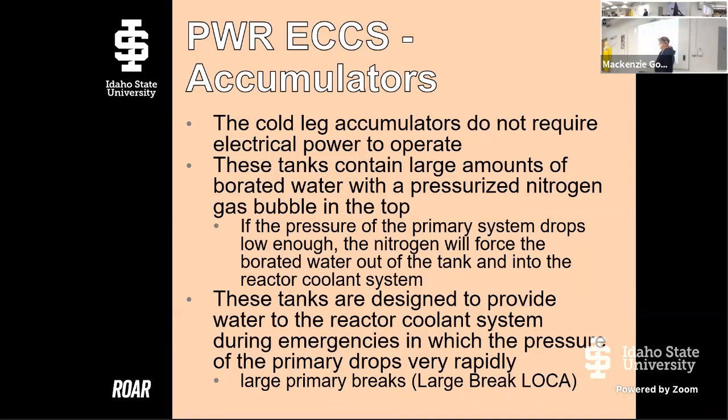Our cold leg accumulators are actually our biggest accident safety system, because if you've lost pressure in your reactor vessel, you've lost a lot of water, that's when these will automatically inject without any power, without any mechanical system. That nitrogen gas bubble is just constantly pushing the water, and once the pressure in the reactor vessel is not sufficient to push back, that water just drops in. So this is our large break LOCA system.